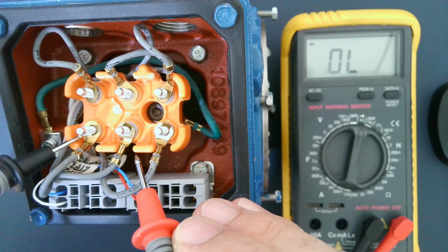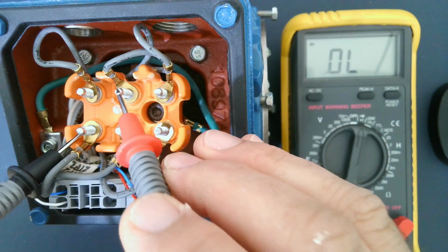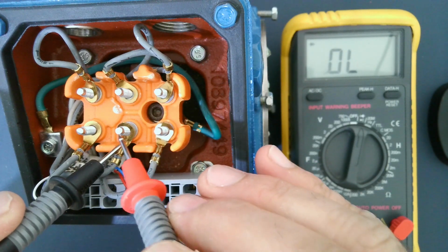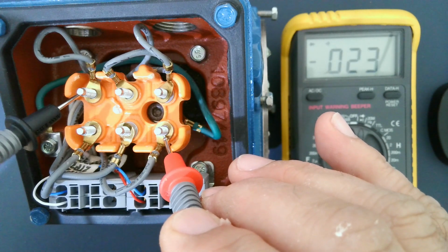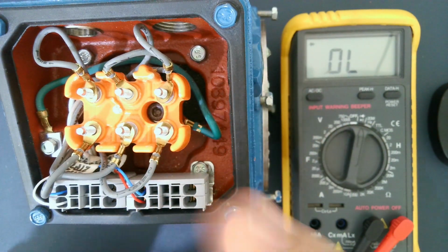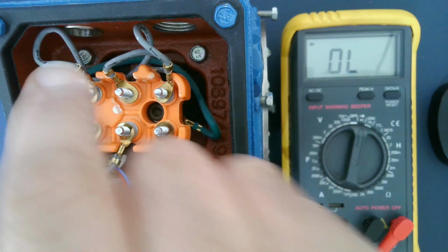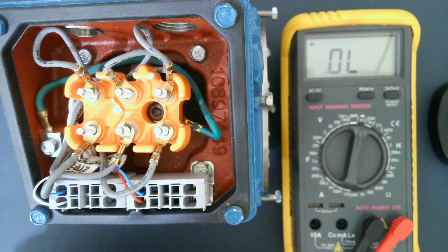But if I connect this one to this one, they are the same phase, so that one will be something like U1, and that one will be U2. And that one will be something like V1, and that one will be V2. And that one is W1, and that one will be W2. If you like, you can make different arrangements. You can move that one here and make U1, U2 here, V1, V2 here, W1, W2 here. It depends on you, whatever you like.